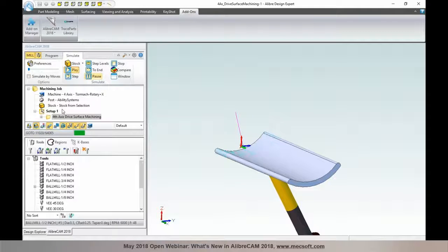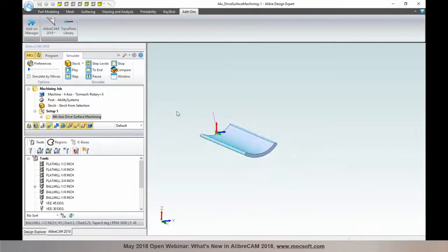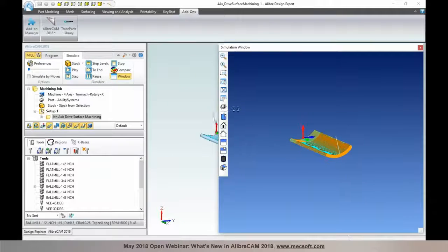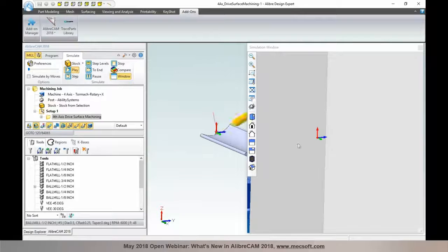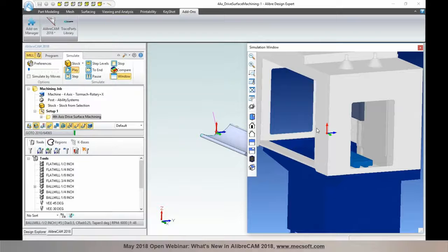Now let me interject here and explain what true 4-axis means. When we say true 4-axis, what we're talking about is that the tool and the table are being moved in four completely different axes. So you'll have the X, Y, Z motions for the tool, as well as an angular rotation of the table or the head. So that's what we're talking about when we say true four-axis. In our other toolpath methods, usually what happens is the Y or the X, depending on your machine tool configuration, is locked. So the tool moves in X and Z in the case of a rotation about the Y-axis, as well as a rotary axis. So in reality, you're getting a three-axis, even though it's a rotary motion. But in this particular toolpath method, you're getting all four simultaneously moving axes. So hope that explains that a little bit.